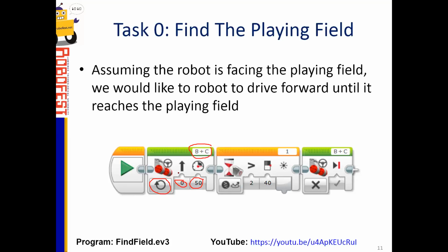And the motor will run while waiting for some event to happen. And the event that's going to happen is we have our color sensor. And our color sensor here is a wait block, waiting on the color sensor to do something: a greater than value of 40, and it's using the reflected light method here. Make sure that when you set this up, your icons look like this. Reflected light, and it's a comparison value, and we're using the sensor plugged into port 1.